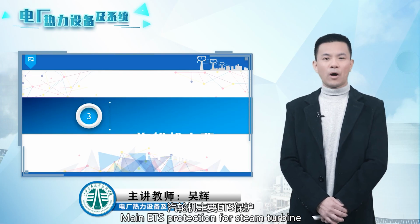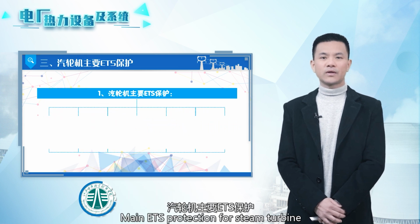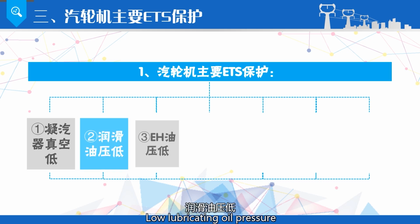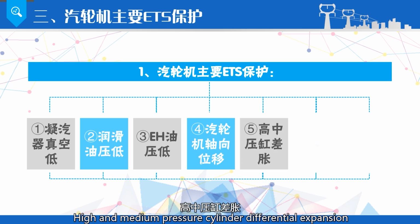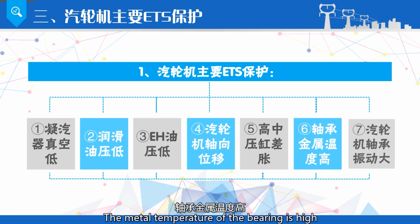Main ETS protection for the steam turbine. Low vacuum in the condenser. Low lubricating oil pressure. Low EH oil pressure. Axial displacement of the steam turbine, high and medium pressure cylinder differential expansion. The metal temperature of the bearing is high.